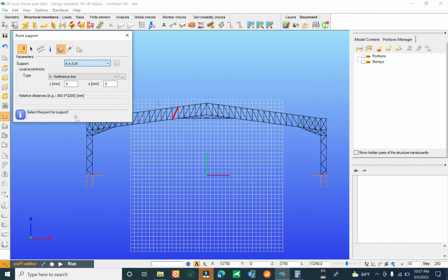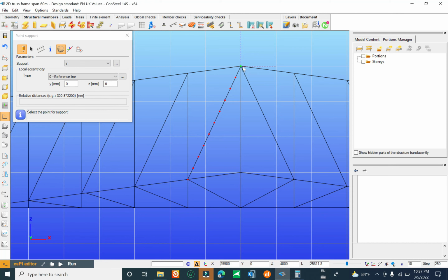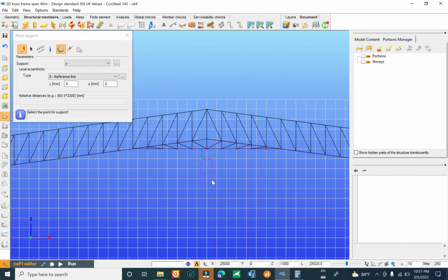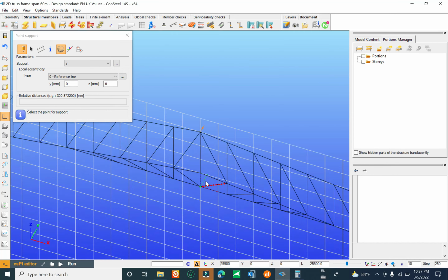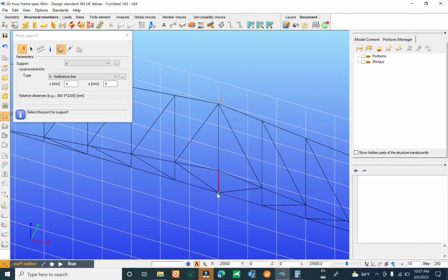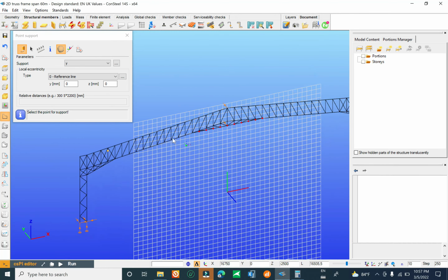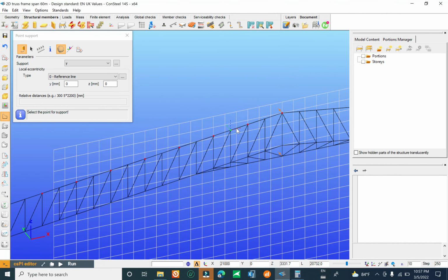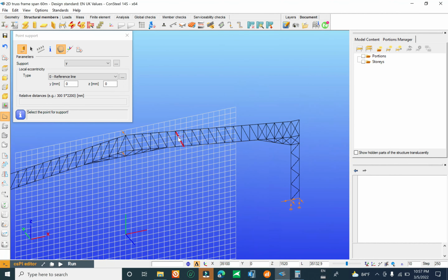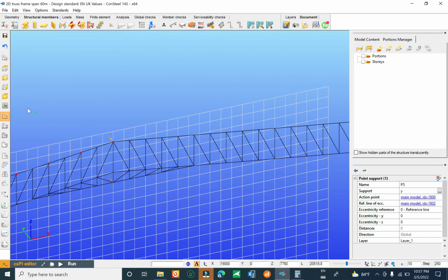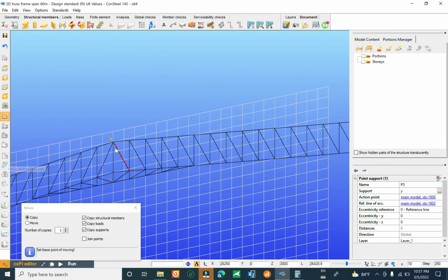and let's start again for the structure and click on model. Now I have to add the insert direction by clicking this one and this one, and you have to make sure your support is set properly. Okay, try it again. Now you can copy it, or you can click it one by one. In this case I want to copy it. Click on here to here. You can click one by one, or you can add the number of the copy.